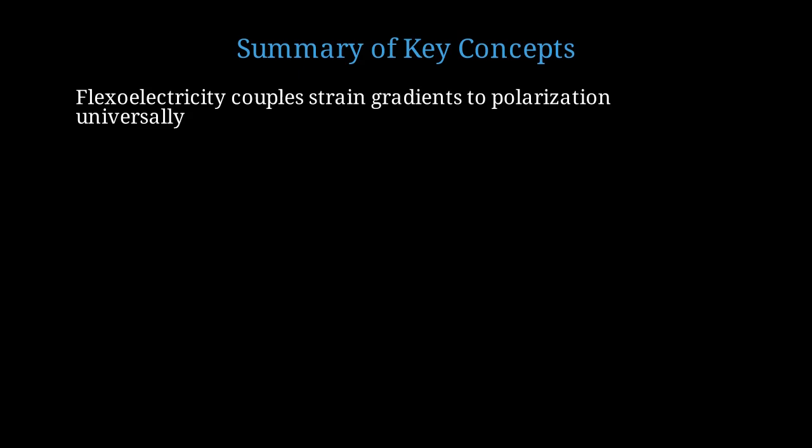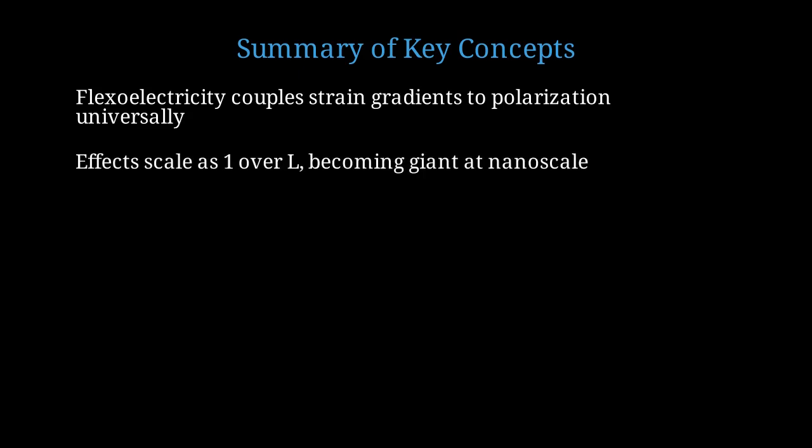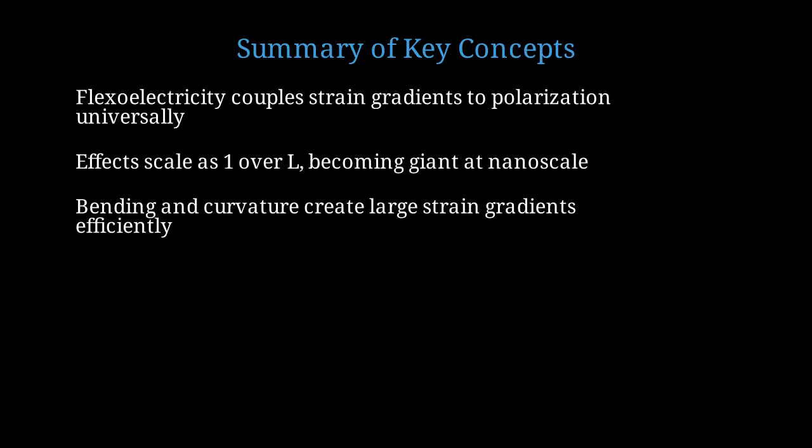Flexoelectricity is a universal coupling between strain gradients and electric polarization, present in all dielectric materials regardless of crystal symmetry. Flexoelectric effects scale inversely with characteristic length, becoming giant at nanoscale dimensions below 100 nanometers. Bending and curvature are particularly effective at generating large strain gradients, with gradients scaling as 1 over radius squared.